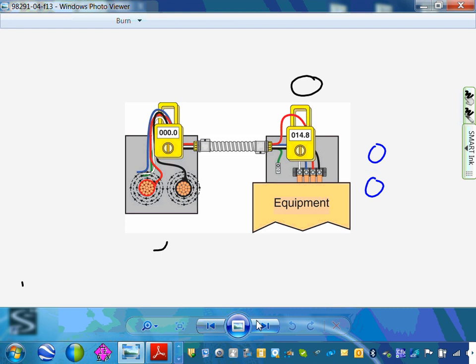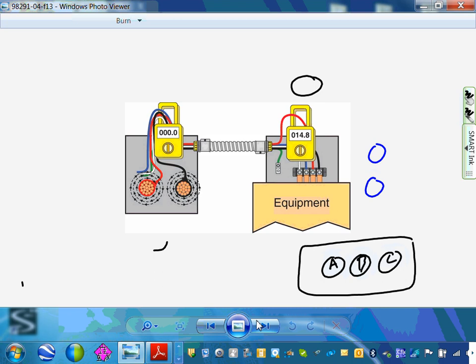Inductive heat, we talked about the inductive heat, guys, why you have to bundle it together. When they bring a single conductor cable into an enclosure, guys, you know what they do? They don't bring the bigger cables in one hole by itself. They cut a big chunk and they bring all of them in the same cavity. So if here's the bottom, one way is to bring the cables, typically bigger cables. Here's phase A, phase B, phase C. You never want to do that. If you do it, and this is metal, especially steel, it's going to be hot, really hot. You're doing inductive heat.